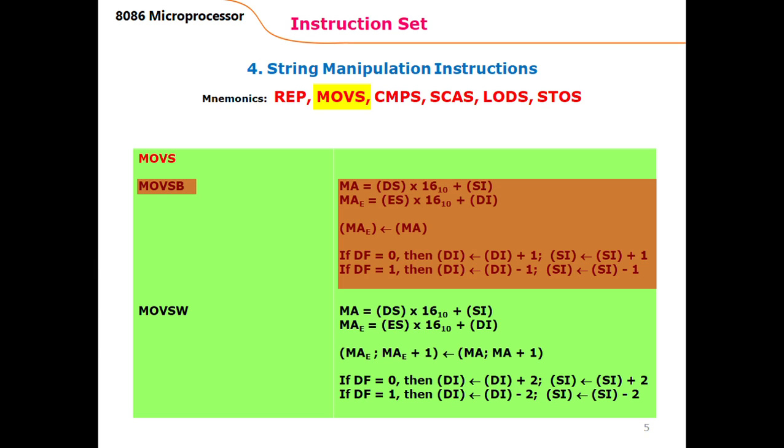So introducing 4 zeros in the binary, or introducing 1 zero in the hexadecimal at the least significant position, is equivalent to left shifting or multiplying by 16 in the decimal system. This operation makes the 16-bit value from the data segment a 20-bit address.